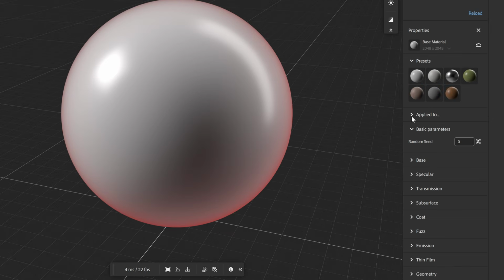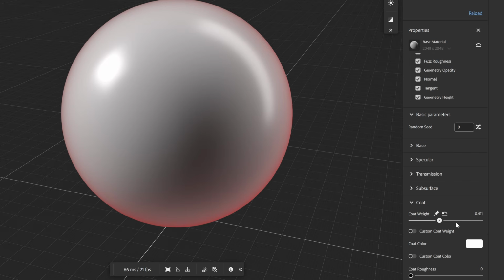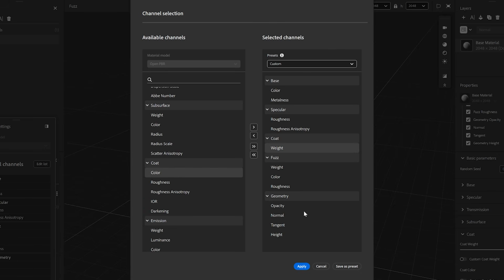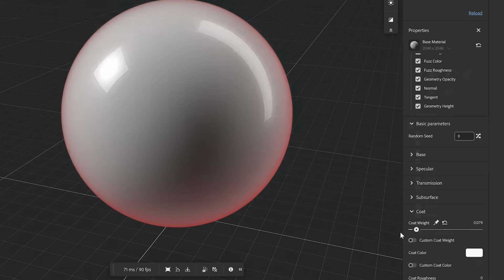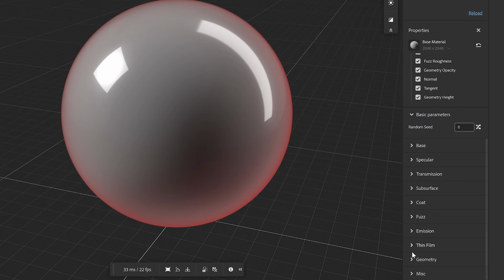Once the material is created, inspect the results in the Properties panel. Here, you will find all the channels we previously configured. You have the power to toggle these channels on or off depending on the specific needs of your 3D scene. This list includes your standard PBR layers as well as any specialized channels you've added. If you change the parameters of a channel that isn't in the list, you have to add this channel manually before. As you can see here, they have been renamed according to the OpenPBR standard. With this organized structure, your material is now ready for fine-tuning and export.